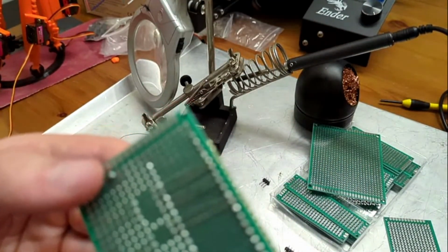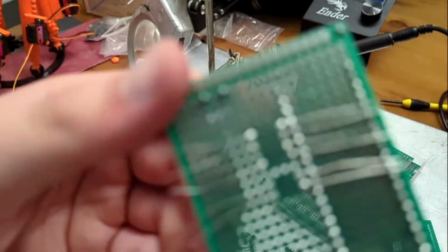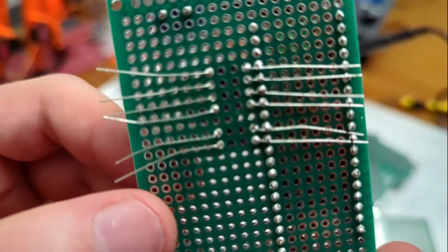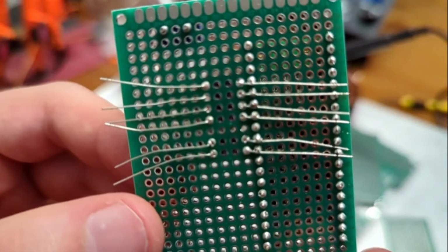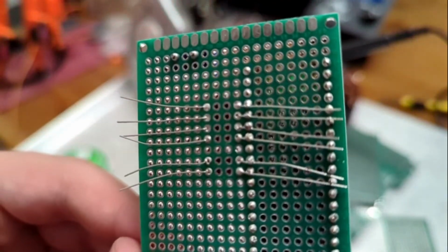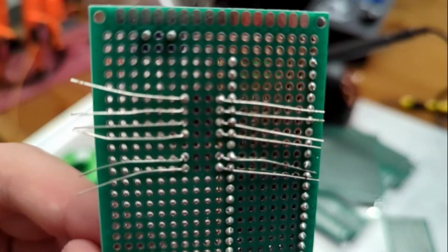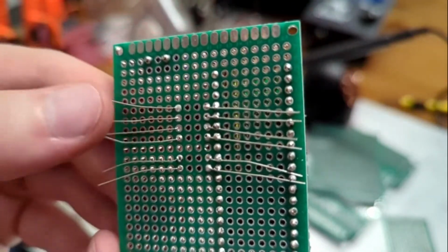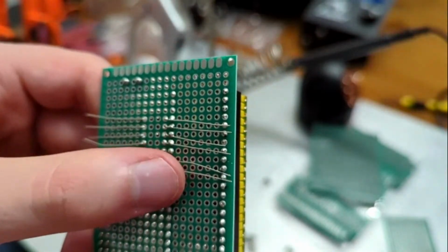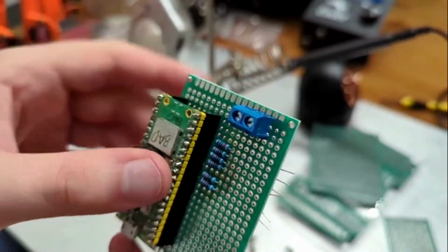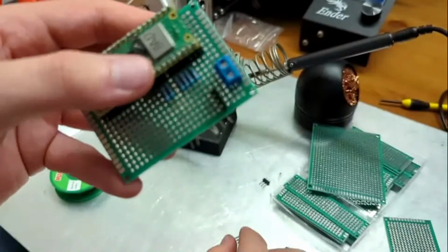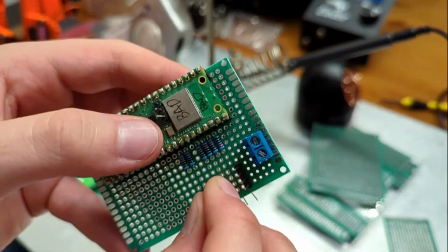And I just do a little visual inspection. See if I can get focus. I like to do a little visual inspection to make sure I haven't accidentally crossed any leads or not used enough solder anywhere. And to me, this solder joint is looking pretty good. I'm liking how this all turned out. So I'm going to cut these leads off here because I know that's as far as I need them to go. And then over here on the other side, I'm going to start soldering on these other wires,